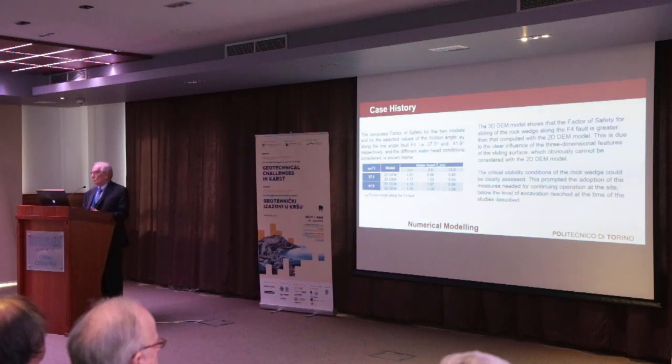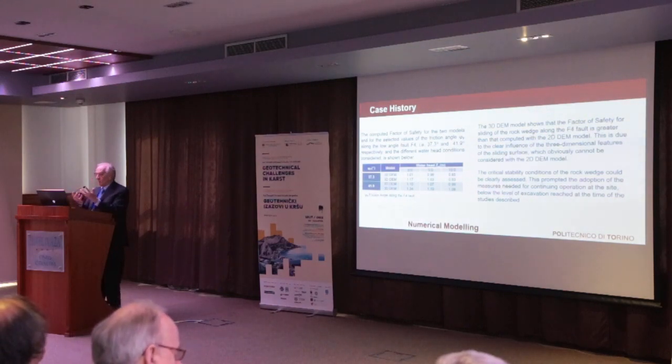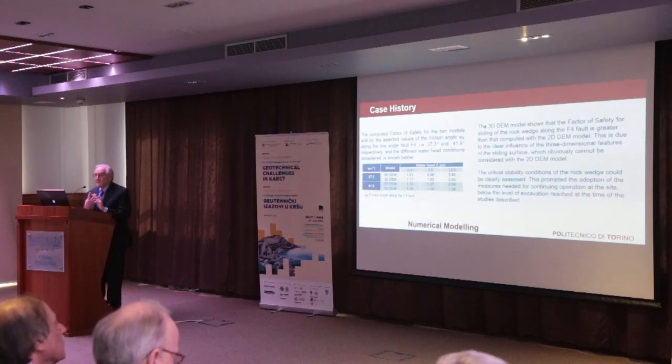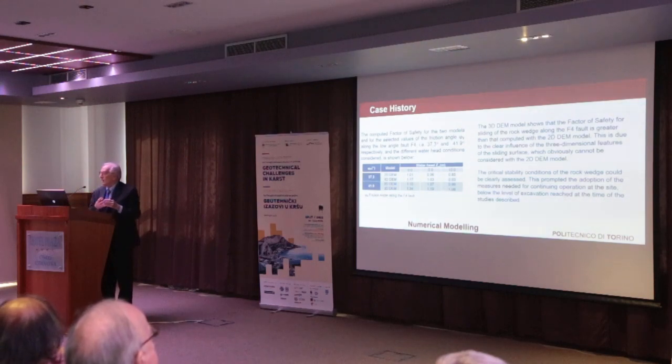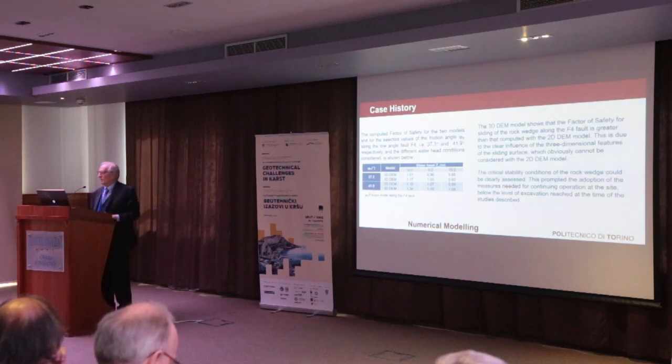And again, you can do modeling. You can have in your mind different scenarios, and you can reproduce the scenarios. I'm not able to show this to you because of time, but I could show you by using the realistic three-dimensional and two-dimensional modeling under the different assumptions. I remove the rock wedge partially. I do some stabilization along the surface of the shred, like the rectangle. And I can show you what is going to be expected.